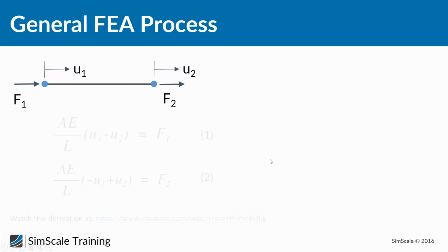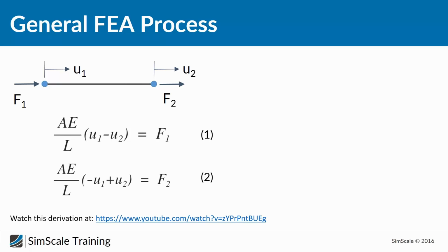So it's a one-dimensional element in the end of the day. And if you take a look at the nodes, we know we have a force at every end of this beam, and basically we can write out this equation describing the equilibrium of forces and displacement for every node. So here we have F1, and this force F1 can be calculated by taking into account the displacement of this point and the stiffness.